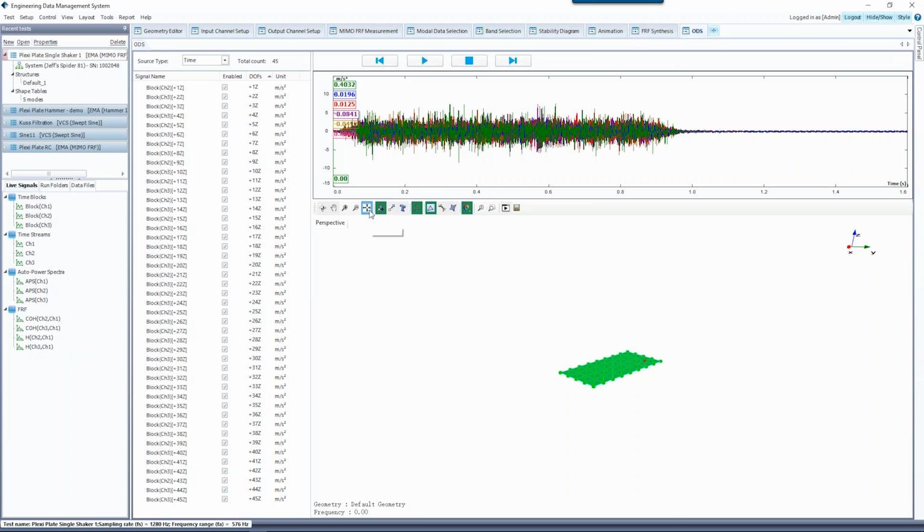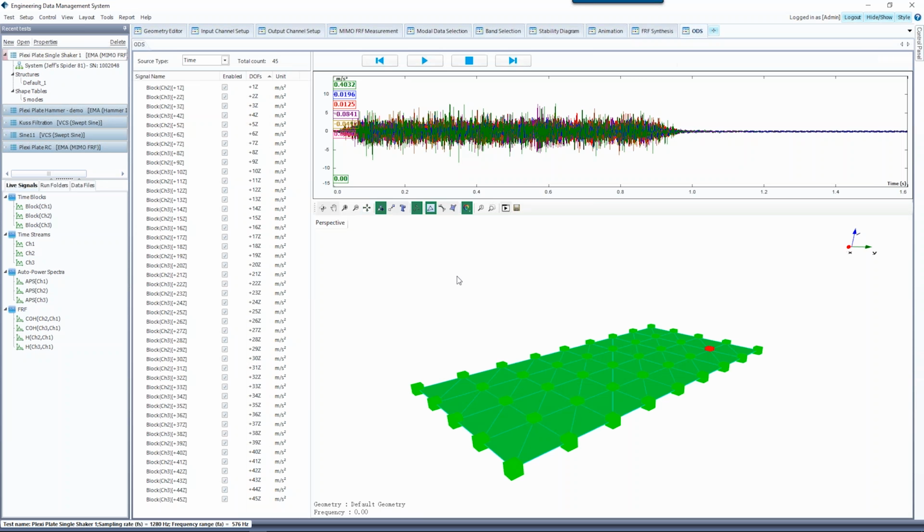So with the modal shaker, the excitation force can be controlled, so the response level is also relatively scaled. So it would make sense to do this time domain animation, or say ODS analysis. And another way is if you have recorded data, we also support that. You can bring in this recorded data with every point and direction labeled, so it will associate to your geometry and do the time domain animation.